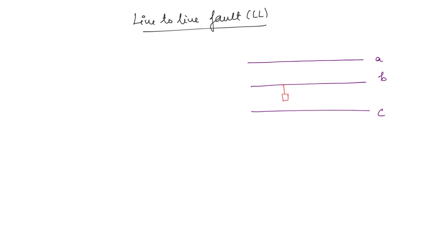So here you have the fault impedance ZF. Now what will happen? The current IB, whatever is there, will entirely flow through here. So IB will be equal to the fault current. And what about this current, IC? So you can see that IB will flow like this. This will be like a return path, right?